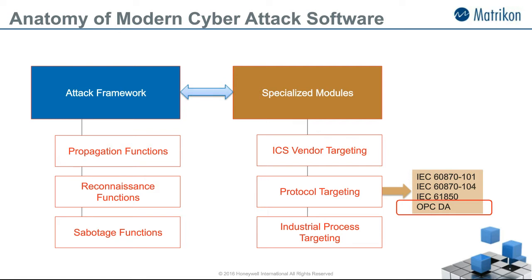It can find what OPC servers exist on PCs to help better profile which PC you're on, whether it's an office PC or a control floor, shop floor type PC, where it's connected to various types of controllers. Based on what type of OPC servers you find on that PC, it lets you know roughly what that PC is being used for, right? So part of the profiling and the espionage type function, or the reconnaissance, that the malware was doing, again, it was using these specialized modules.